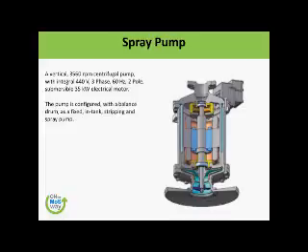here. So the pump is configured with the balance drum as a fixed in tank, and what it is used for is basically the stripping. So you can see a very small thing. Whatever the cargo is left after the main pump stoppage, this is the pump which pulls it out. And this is the pump we also use for our discharging ashore, pumping to create the boil-off gas when we are creating boil-off gas.